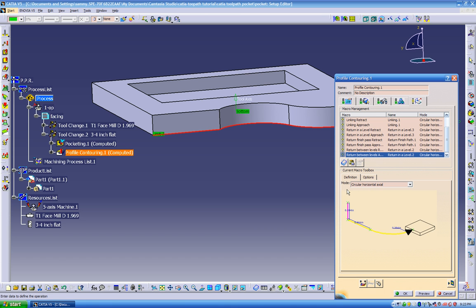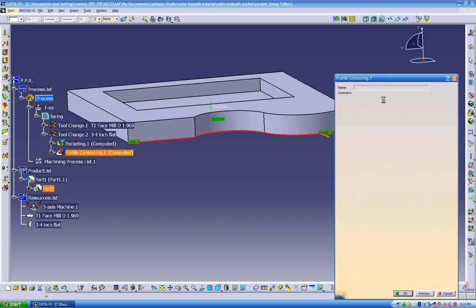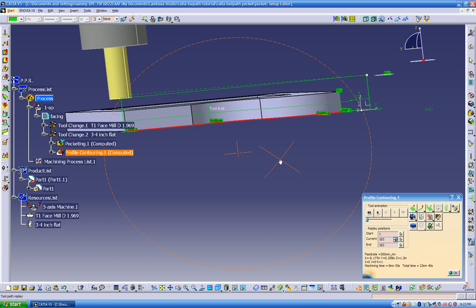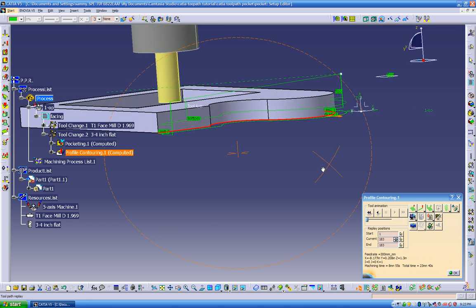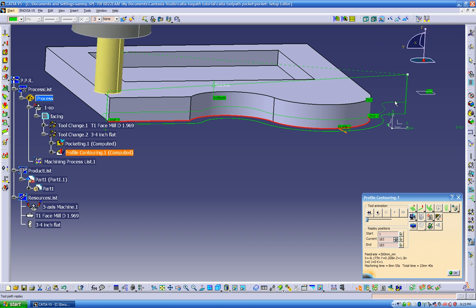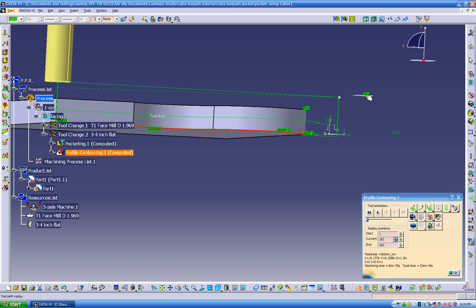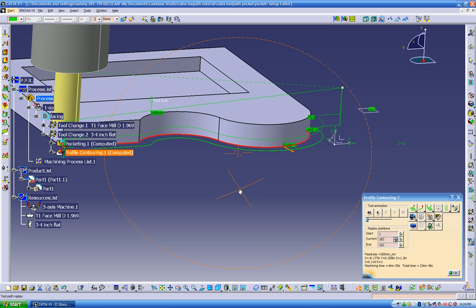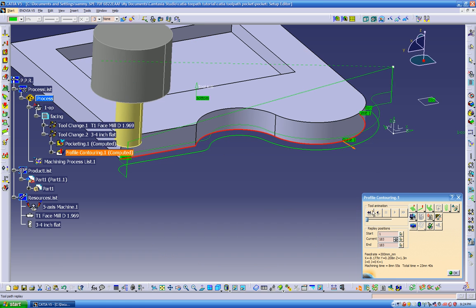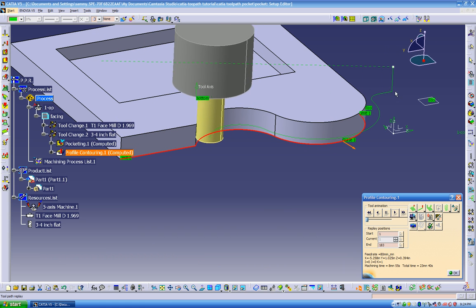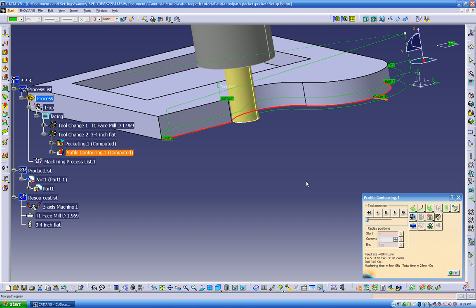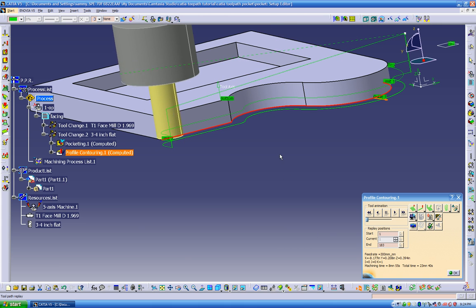And also we can add planes to these guys. You can go back, build by user, click on the plane, select your plane, and also you can do this. So we can bring your tool all the way to the top. See right now how nice it looks. Every little pass leads outside, comes back in, and goes all the way to the top, which is this plane that we selected. And this is beautiful. So let's watch it. See, it plunges outside. We got 2 roughs, and this is 1 finish.